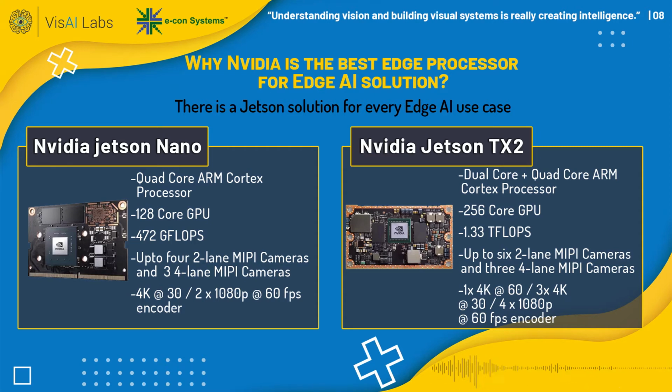When you choose a processor, look at the number of cameras you need. The Nano can support up to 4 2-lane and 3 4-lane cameras, so it can practically have 4 4K cameras. Also look at the encoder. The capability of the encoder is important for applications like remote monitoring or telepresence.